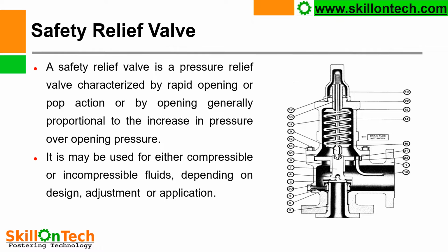When the inlet pressure of air, gas, or steam increases more than the set pressure of the safety valve, it will pop up. It may be used for either compressible or incompressible fluids depending on design, adjustment, or application. But these safety relief valves are generally used for air or gas services.